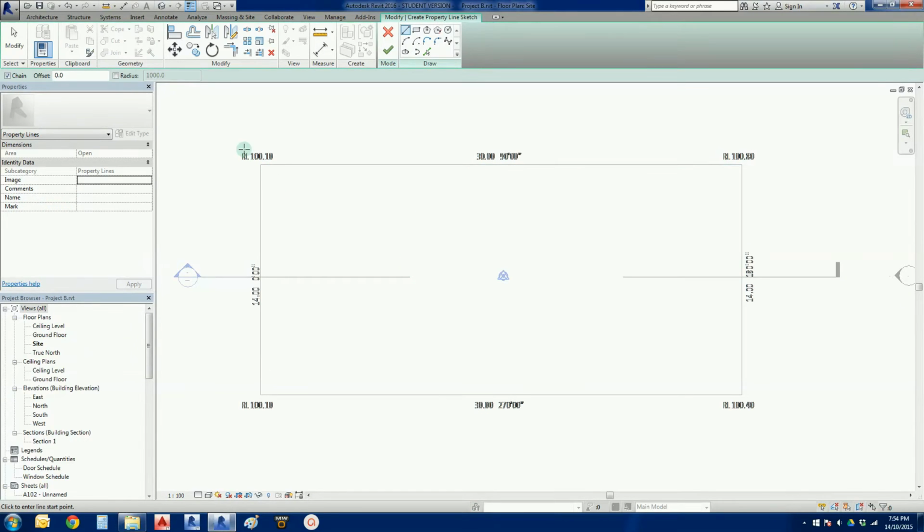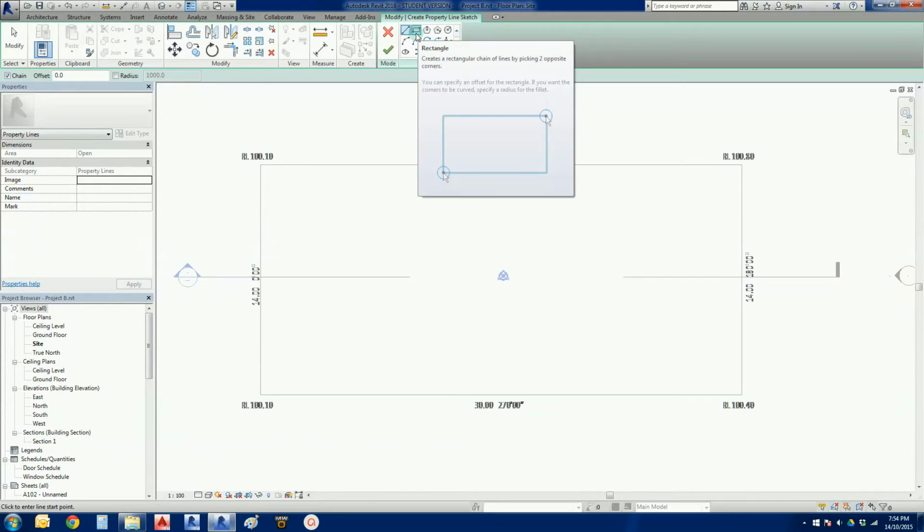Now we're going to see that our CAD file is grayed out because we are in sketch mode, and we've got our drawing tools here. All we need to do is basically pick up these four lines here. So it's a nice simple one. Now I could just draw the lines there, or being a perfect rectangle I could use my rectangle tool there.